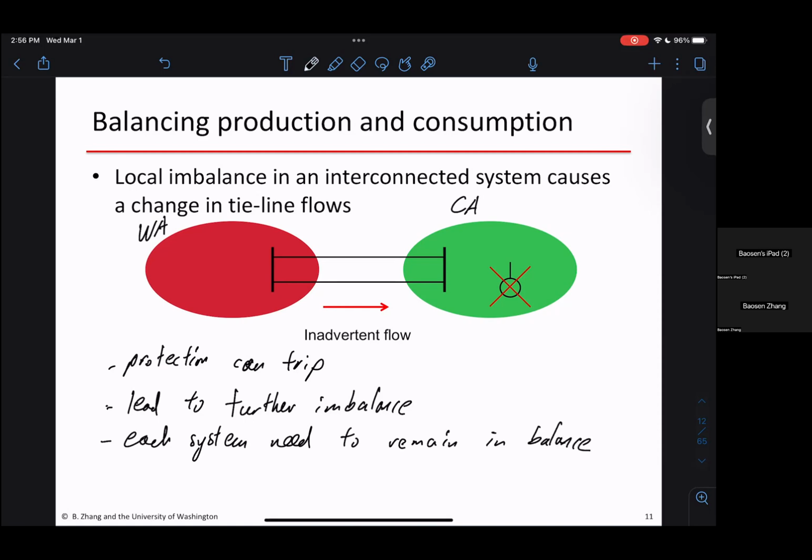So when you're doing your resource allocation for California, often you cannot count on, if I lose a generator, I'll get power from somewhere else. You have to maintain your own balance. Say California has a wildfire potential and they trip some lines. Can we not shift more power to California and help provide power from our state? Often you're limited by this issue. You're often limited not because of a nominal case. We can often deal with a nominal case of how much power we have to send. But you always have to think about, if something goes wrong, you want the entire system to still be okay. That's often the limiting factor for us.